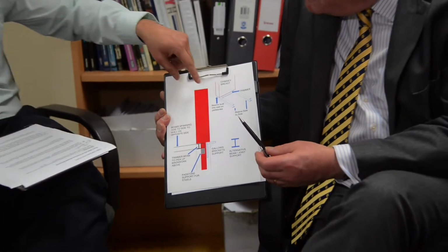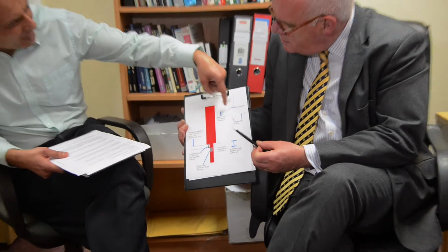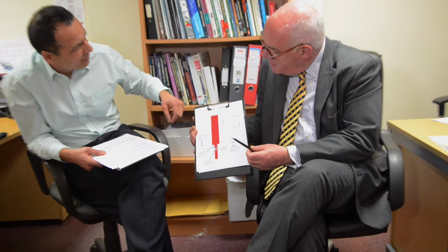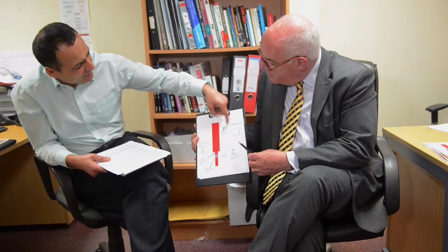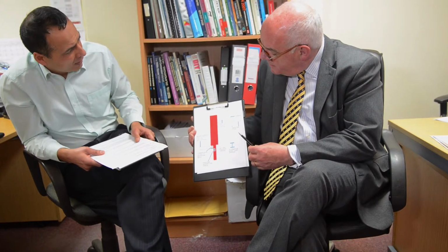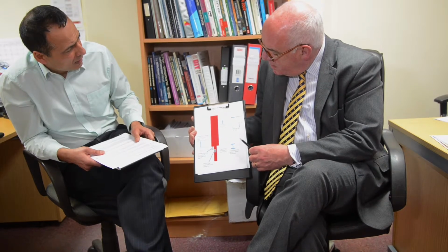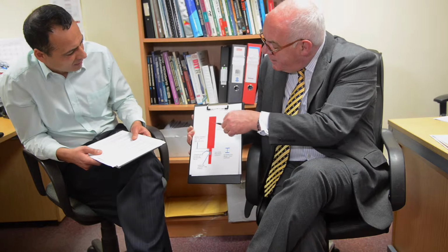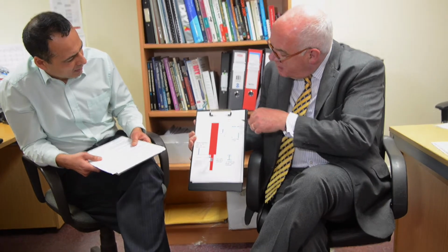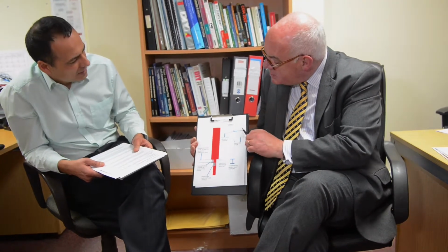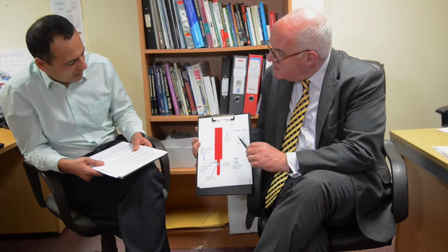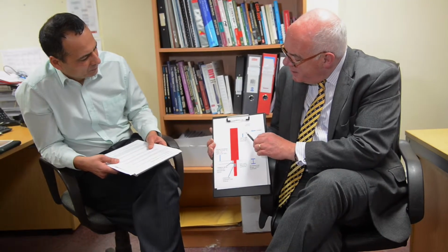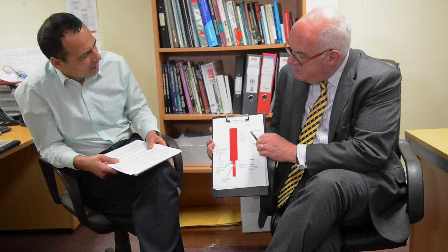Could you have a situation where you have a steel support actually running underneath? Because I've come across that scenario where it's running underneath the chimney breast wall, and then bearing onto internal load bearing and external load bearing walls. Yeah, I mean, you can have that scenario. If you've got cross walls in this direction, and perhaps a rear wall in this direction, then you can span between those two walls. Absolutely, it's just providing sound and competent support to the chimney breast on your side.